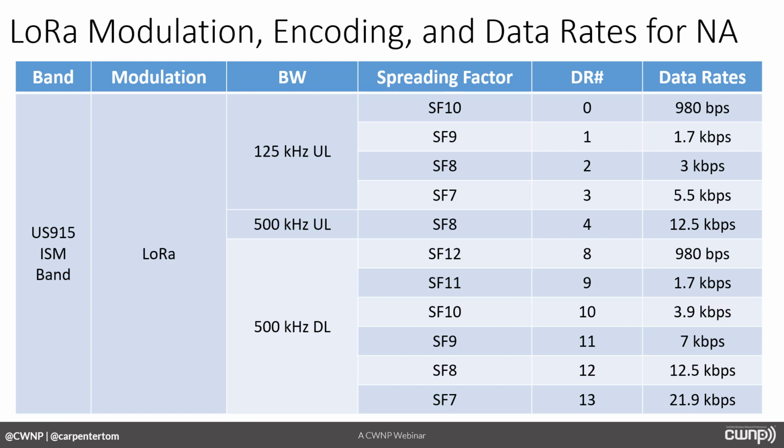And the gateway needs to be able to hear that. And a gateway could potentially listen on 8 different channels at the same time. So what does that mean and why do I care? Well, what it means is that the system must address the reality that the gateway wants to be talking as little time as possible, right? So we want to default to, whenever possible, using higher data rates in order to accomplish that.